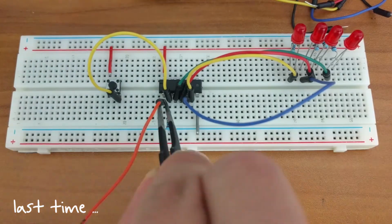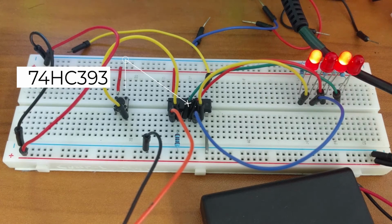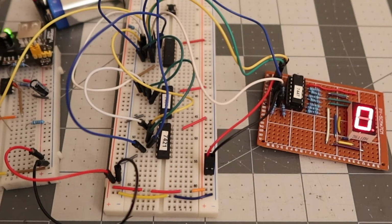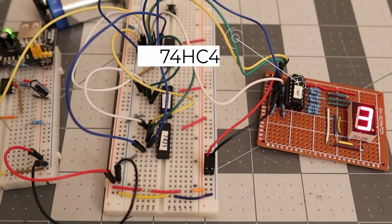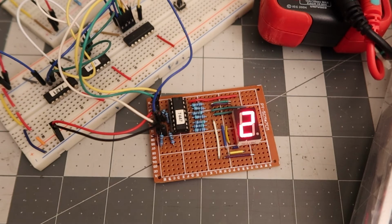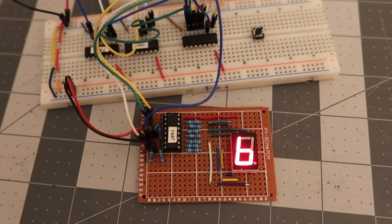In my previous video, I built a 4-bit counter using the 74393 chip. To display these numbers, I'm going to be connecting it to a 7-segment display using the 7447 chip. You can see that it displays the number correctly, however, being that it is a 1-digit display, anything after 9 will just be gibberish. In this video, I'm going to limit the output to 9, so that way we'll have a 0 to 9 up counter.